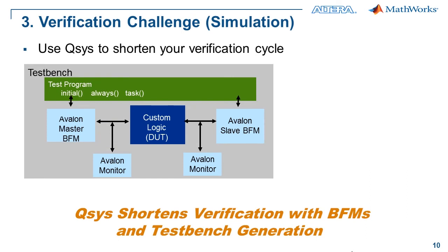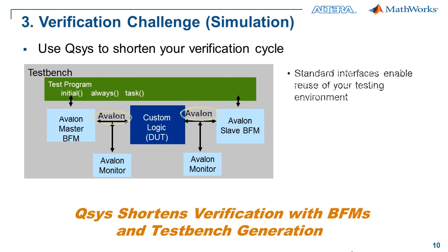Now let's look at the verification challenge. You can shorten your verification by shortening the time you spend on simulation. Take a look at the device under test, which is connected to bus functional models and monitors, all wrapped up with a top-level test bench file. Here are some areas where Qsys can help you get your simulation started faster.